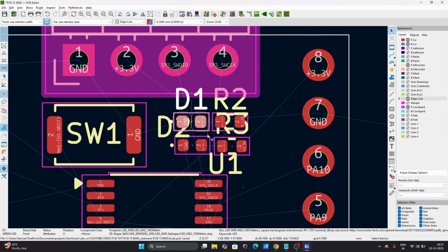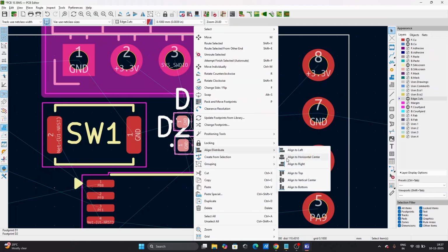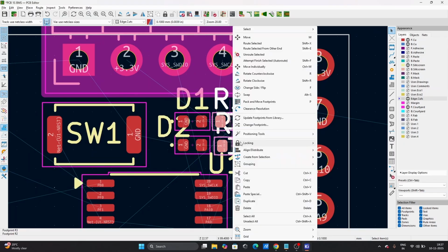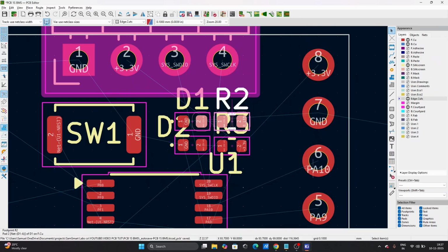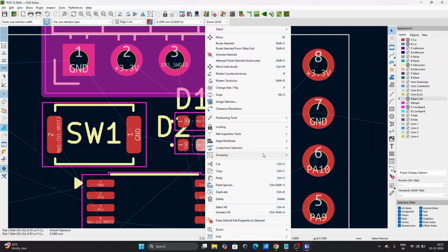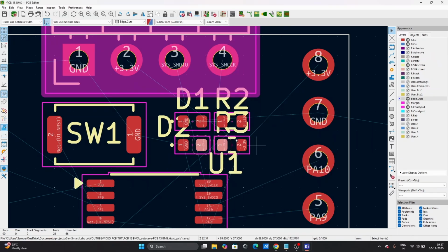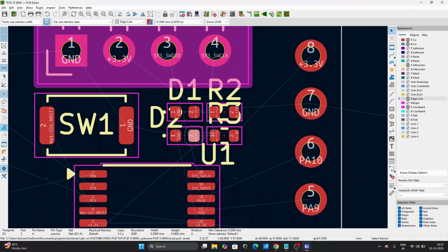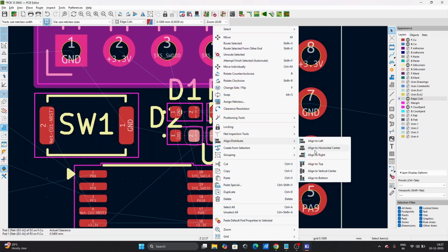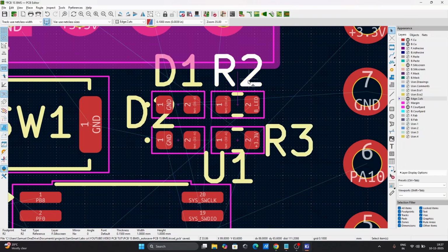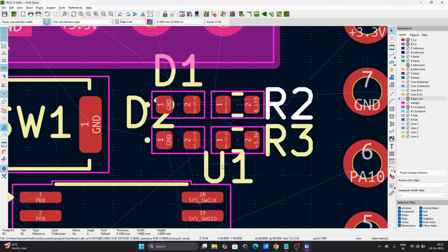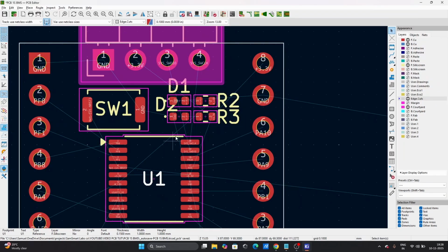So I'll just get these guys aligned. I like them to be beside each other. And to get this aligning option, you select both components like here and here, and then you right click and go to align. So you have here our resistor, you can put this on the side, not necessarily needed now. Just put this MCU here.